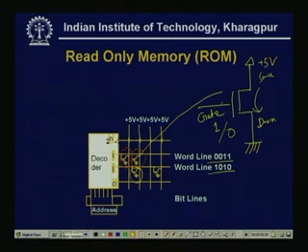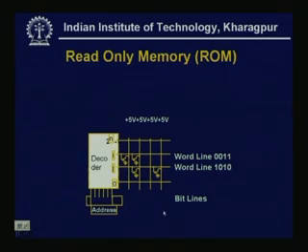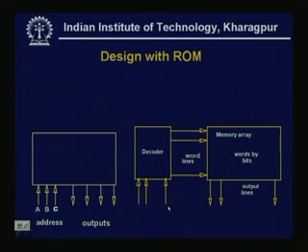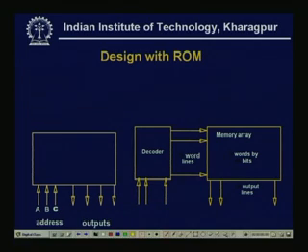Now, how can this ROM be used for designing a circuit? Say this is my ROM with 3 inputs and 4 outputs. Now, first this can be realized as if it is a decoder.